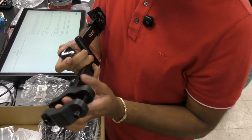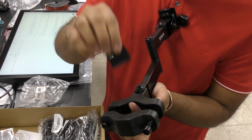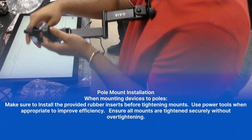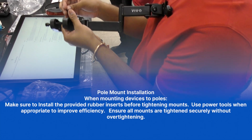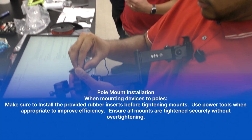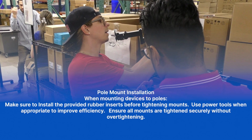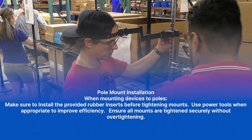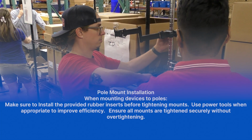Section 5. Device mounting. Pole mount installation. When mounting devices to poles, make sure to install the provided rubber inserts before tightening mounts. Use power tools when appropriate to improve efficiency. Ensure all mounts are tightened securely without over-tightening.